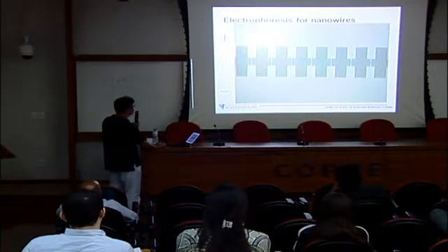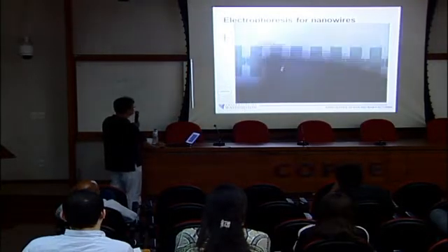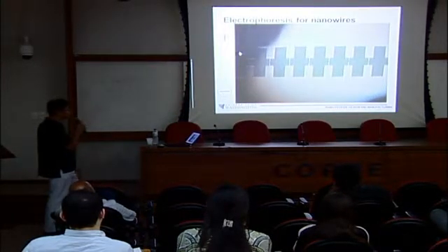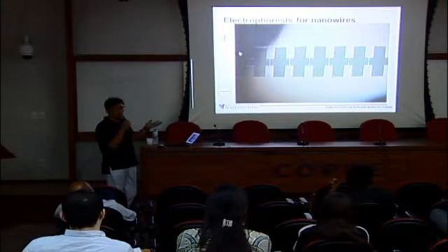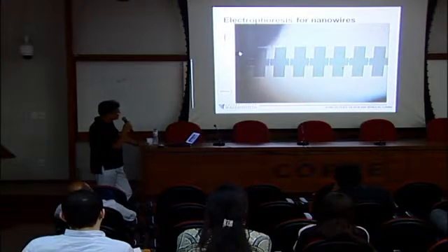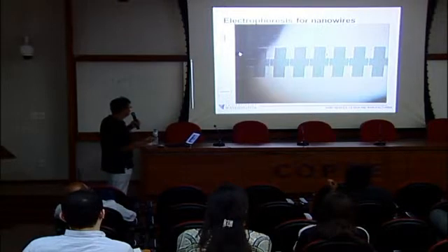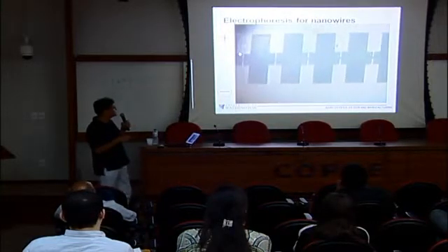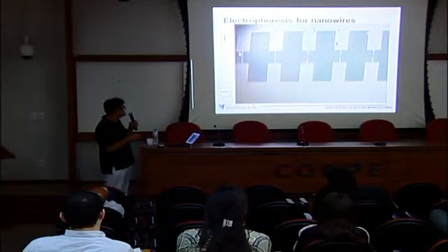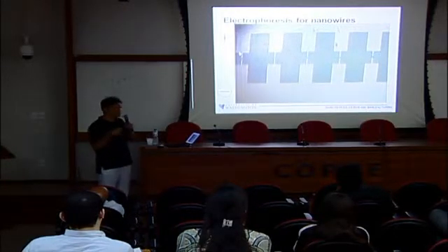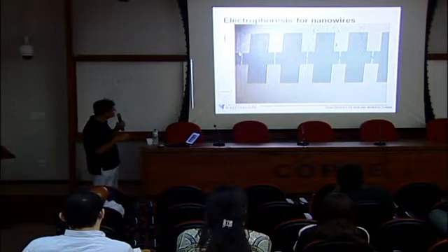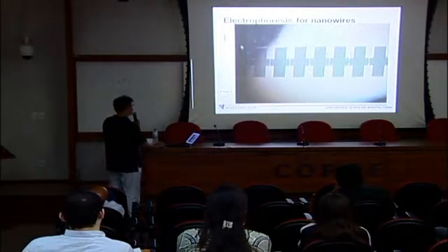So these two are the electrodes, and then we will place a solution on top. Now we are doing the experiment under a microscope, and after 30 seconds or 1 minute, we will see where they go. Then the negatively charged nanowires will be placed onto these positively charged electrodes, right? So they are attached onto that. And the flow here is kind of random, because without a microfluidic channel, we just put the solution on top. So if you see, most of the nanowires are on the positively charged electrodes. Okay?